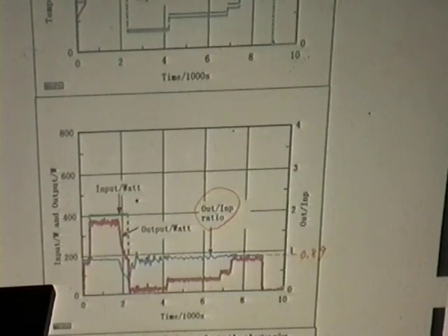According to the result, I can say a steep input change did not affect the heat recovery. This heat measurement system can precisely follow input and output heat. The only difficulty is the method is uncertain at the low input power range because the temperature measurement error was 0.1 degrees centigrade. However, the precision of measurement is enough because input is usually above 70 watts.